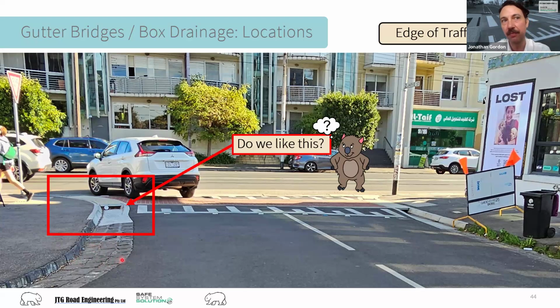And what that does is it typically is placed to reduce scouring, so to reduce erosion and things like that. But it also means if it's grouted beaching, so you've got cement or some form of grout between the stones, it also means that plants just won't grow there. So it serves a double purpose of reducing erosion and also reducing that maintenance burden for curb outlets. Hopefully that assists there for you. Yeah, that's great. Thank you.